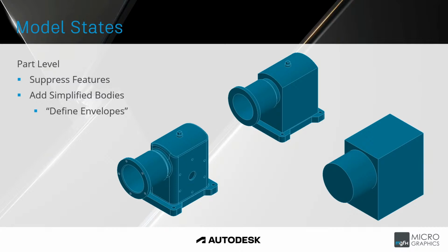So model states allows you to create various states, within which you can suppress features. If we look at these 3 images, in the middle one, all the fillets and chamfers and holes have been suppressed and removed out of the design. The housing was shelled, and the shell feature has been suppressed. And lastly, in the third image on the far right hand side, there is a state where simplified geometry has been added.